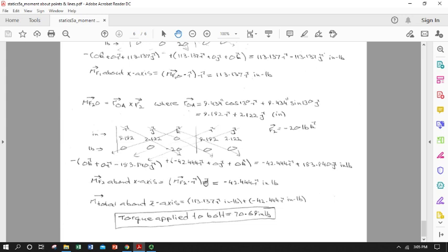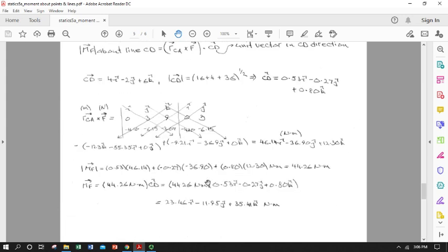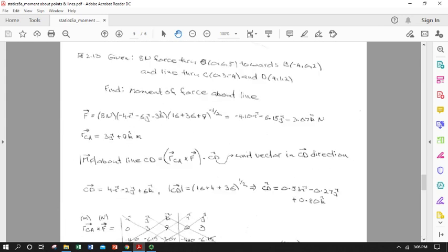So you can go through the previous example, which is a little bit more dry and boring. It's all points. There's an 80 Newton force being applied through 2 points, so this gives you your line of action of the force. And there's some line of interest between 2 other points, and somebody wants to know what the moment is of this 80 Newton force about a line going through these 2 points. Maybe there's a shaft, or there's something they don't want to rotate. So we want to know the rotating torque. Use the same exact type of steps.